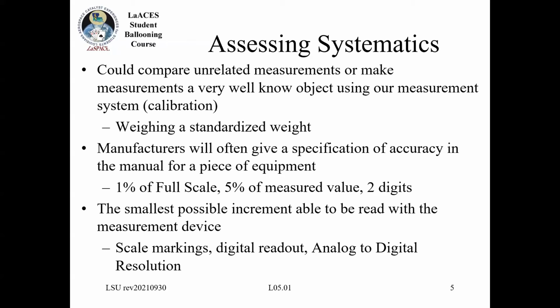So I would say my systematic error is as large as 2 volts in that case. It may also be given as a percentage of whatever the output is. And then also sometimes you'll see it phrased as number of digits, in particular with multimeters. And what that means is it's times 2 of whatever the smallest digit on that particular scale is.